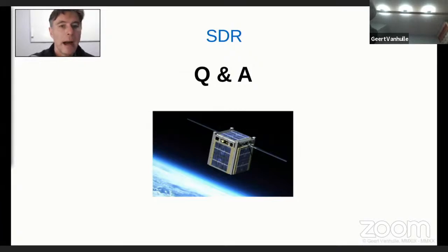So we will add a digital inverse signal of the same amplitude but inverse phase digitally to our sample stream that will compensate for the harmonic that would appear normally at the output of the DA converter.